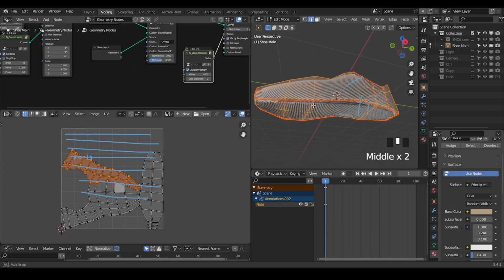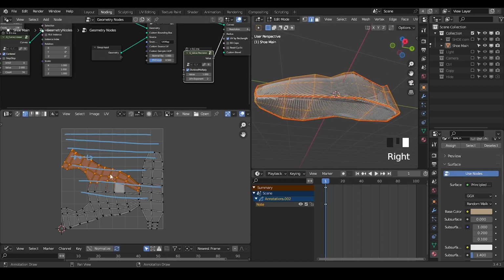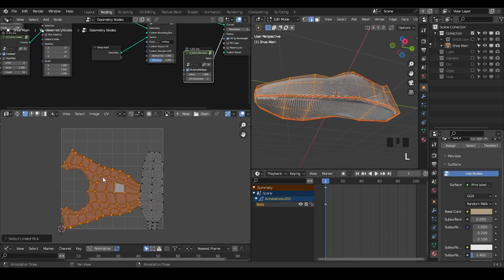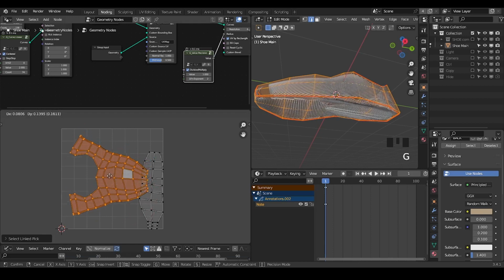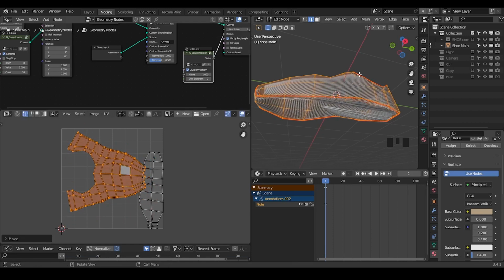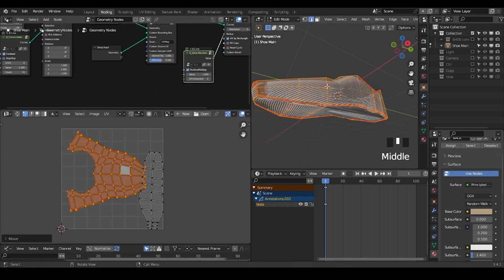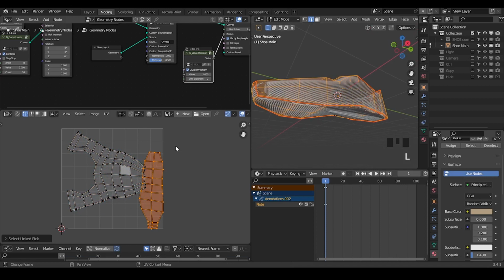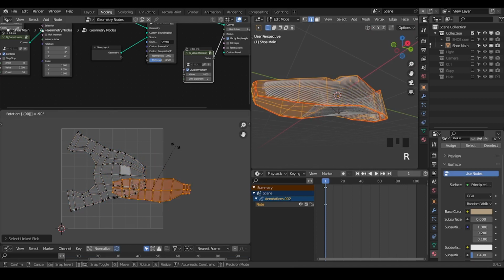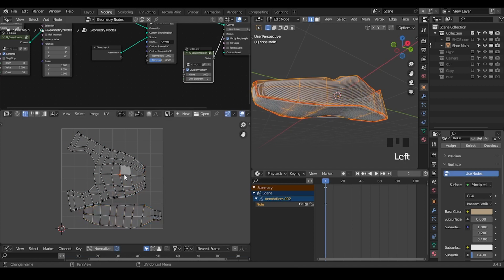For me, in this particular case, I'm just going to rotate this island. In UV editing, you can hit L so that you select all islands at once. By moving that, you can also see how the UV map is affecting our mapping result. Here I'm going to hit L and rotate that by hitting R. Rotate it 90 degrees and put that to the bottom.